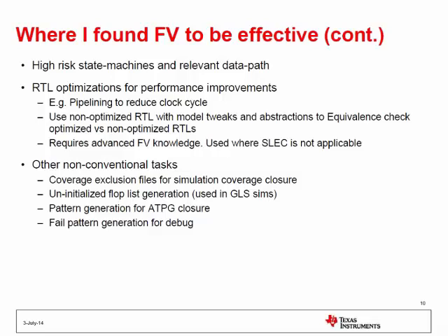And the other trend that I've seen in the last 10 years is the way folks use it in a non-conventional verification way. One thing, at least from the latest Cadence tool, is you can build the coverage exclusion files for your simulation, because you'll see a lot more dead code or toggle coverage based on the tie-offs or static bits and things like that. So you can import your coverage exclusion file by running something on the FV. Another thing is the uninitialized flops. When you go to VLS, you can figure out what the uninitialized flops are.